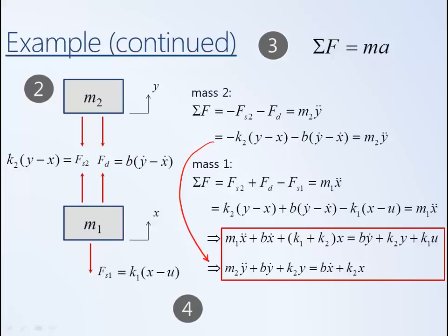In general, for a physical system like this, a suspension, which is in essence a passive system, it should be stable. The natural response of the system shouldn't blow up, i.e. its poles, or the roots of its characteristic equation, should have a negative real part.